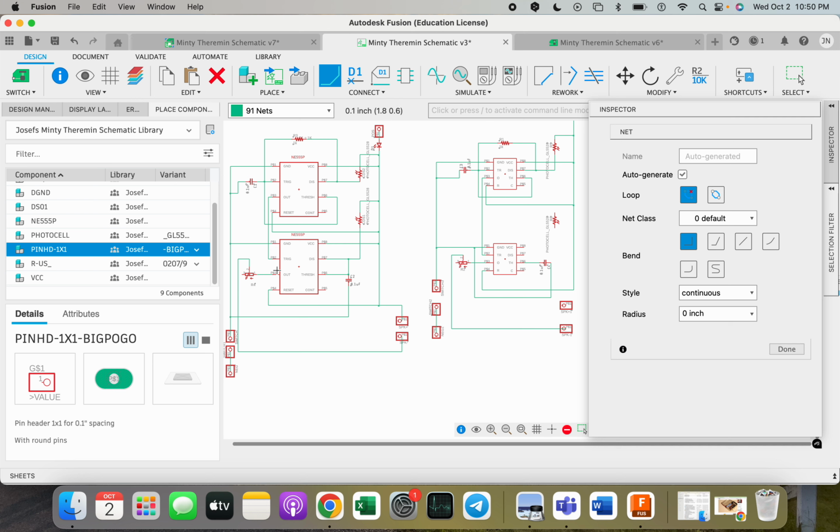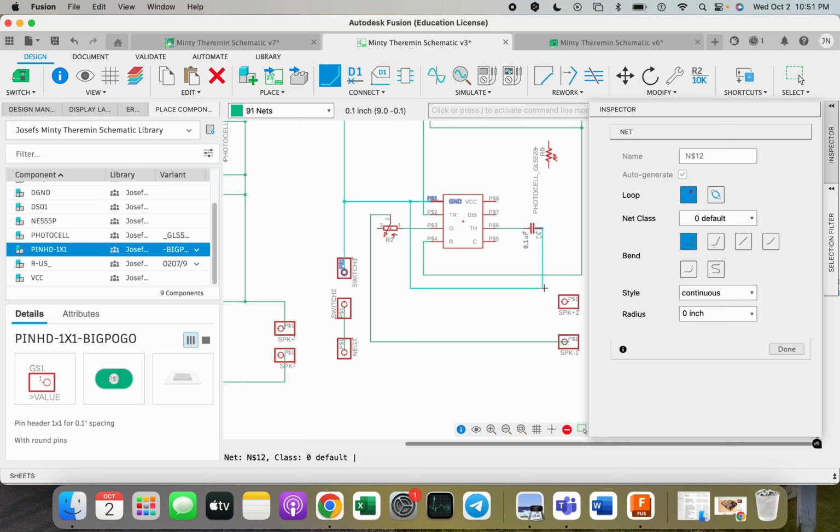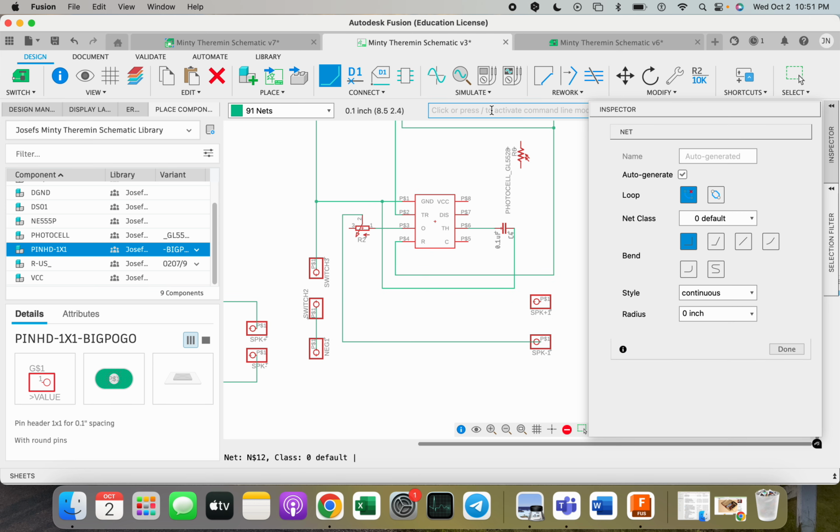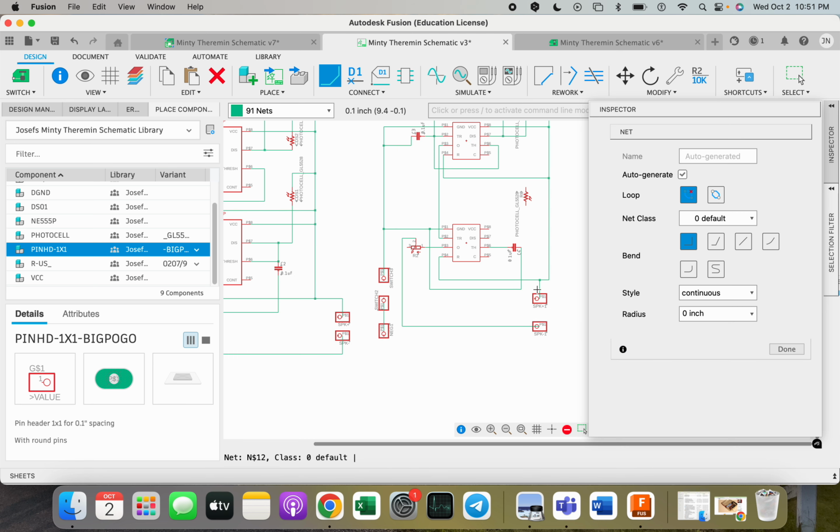So that's pin 3 complete. Pin 4 is connected to speaker positive, and it's connected up. You'll notice that we already made the connection to the positive line up here. So we just need to grab that point, not this one, this point up here. We can connect speaker up to that line to pin 4.